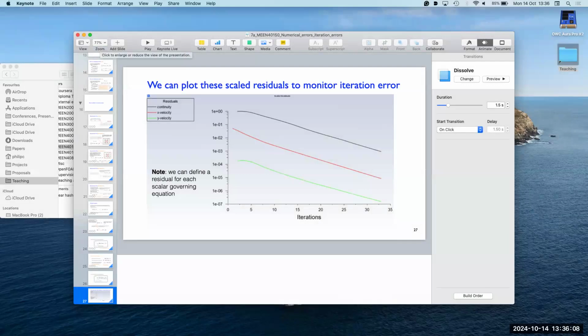So, for example, there's no point in having a very fine mesh, a very fine discretization error, if your iteration error is dominating the solution. So whatever you're interested in, you might do a sensitivity analysis to see if this iteration error affects it. If you're interested in the force on a boundary, force on a wall, you might run that with 2 different iteration error tolerances. And if it doesn't change at all, then it's fine to use the loose one.